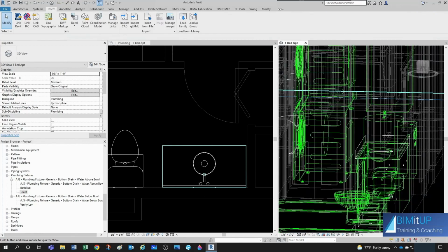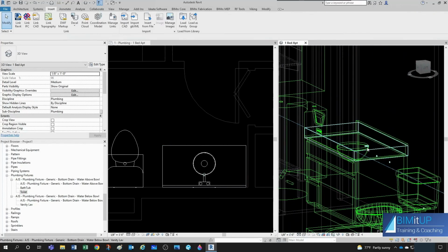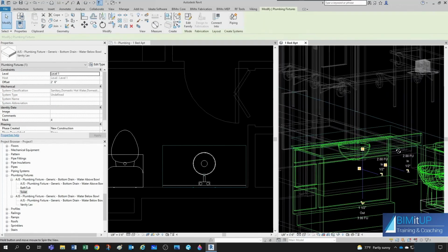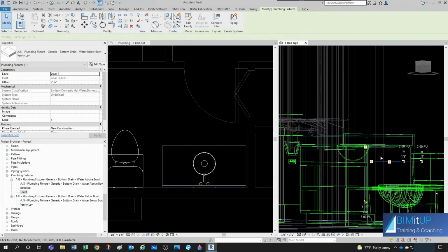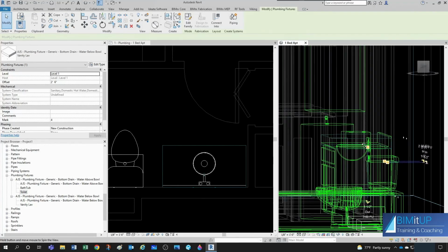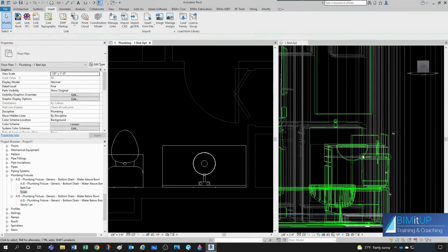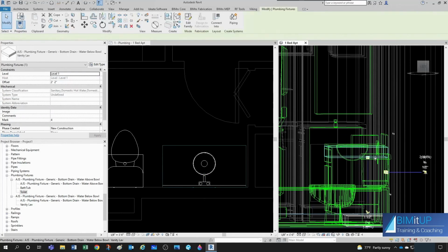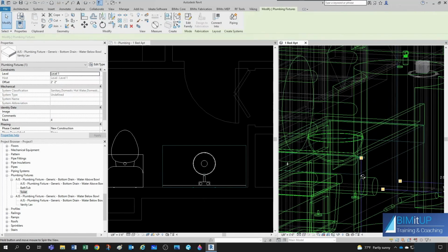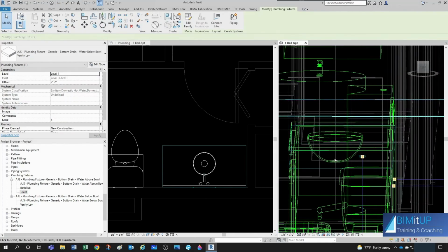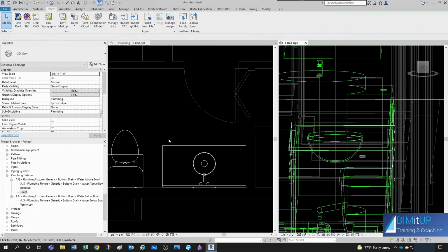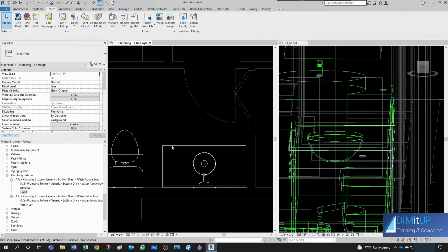Notice that our drain is a little bit too high, and that you can also change. I could just adjust the elevation of this so the drain is wherever I want it. So let me drop it down to, let's say, 2. And now the drain's a little bit closer. Notice that I can also change the location of this drain to be closer to the bowl, and that is changed under this parameter. I'll show you.